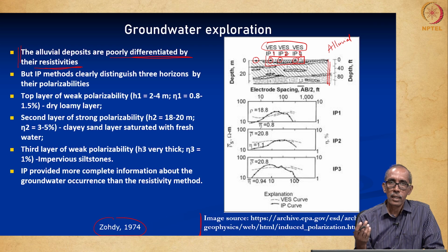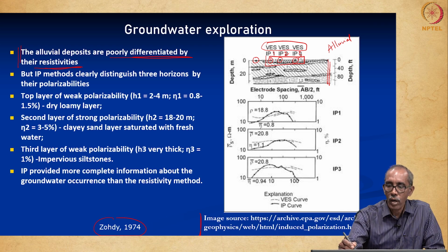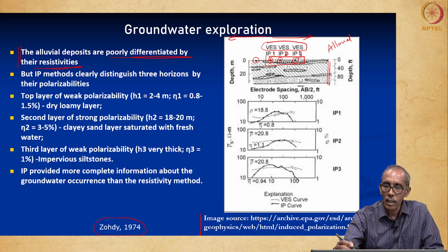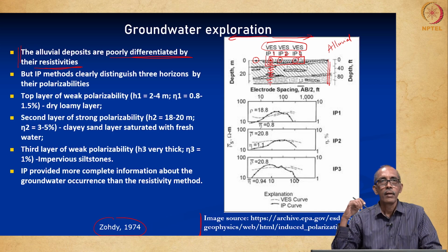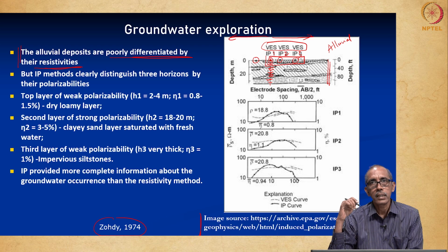What is vertical electrical sounding? In vertical electrical sounding, over this point, we will spread the electrodes symmetrically on either side, and slowly we will move. So, we will end up with data of depth versus apparent resistivity, so that we will know the resistivity of the subsurface at different locations, as I am drawing, please notice, right. However, it was not giving sufficient information, right.